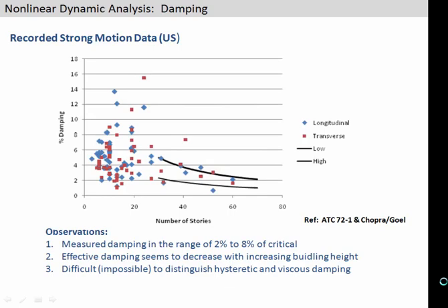You could say, well, how do we know what value of damping? Let's go, after an earthquake, measure the decay in the response of a building, and that's our damping. Well, that would be wrong to put all of it in the C matrix, because what you see about the damped out motion in a building, some of that might be things that you're actually modeling in your analysis through hysteretic response, and it's the part that you're not modeling that you want to throw into the C matrix.